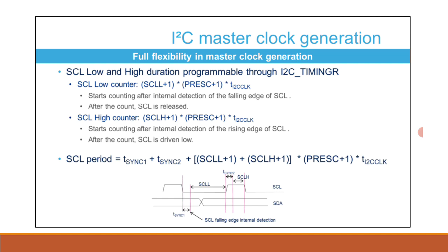The rising edge depends on pull-up resistors and SCL line capacitance. The falling edge depends on I/O port parameters defined in the datasheet. In order to properly configure clock speed, these edges can be either measured or calculated.